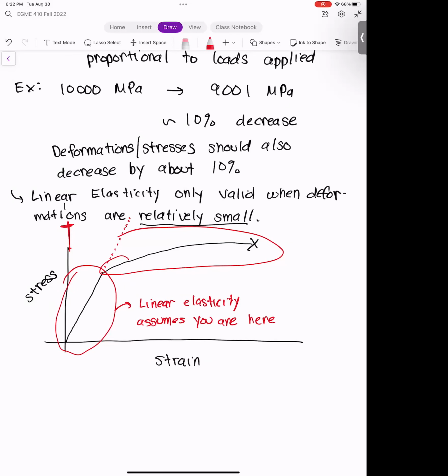Yeah, so that's kind of why I bring this up. FEA is great, but you have to realize that a lot of the complexities that you understand for how materials behave, how thermal materials behave, you have to explicitly determine or express that in ANSYS. Otherwise, it's going to assume something else. So knowing the limitations and understanding the equations that go underneath the hood are important for what I call responsible use of FEA.